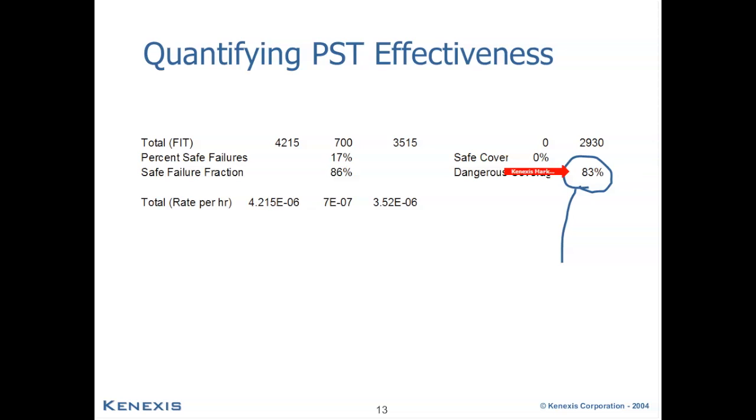So that is the methodology. If you wanted to provide a very rigorous analysis to justify the number that you're going to put into your calculations for coverage provided by partial stroke testing, this is the methodology that we recommend to use to do that.